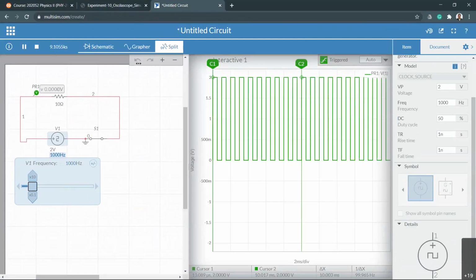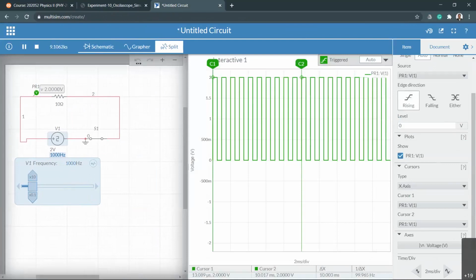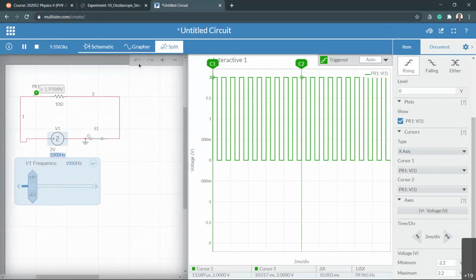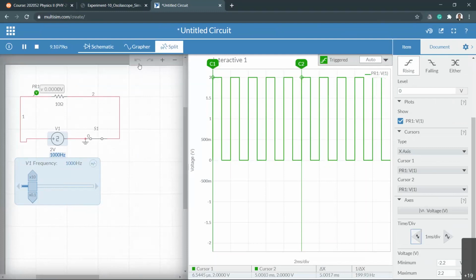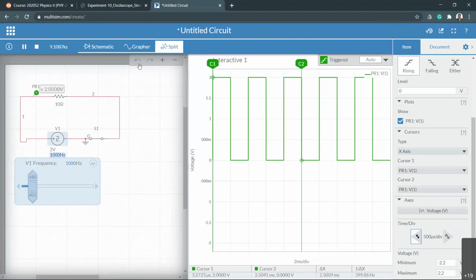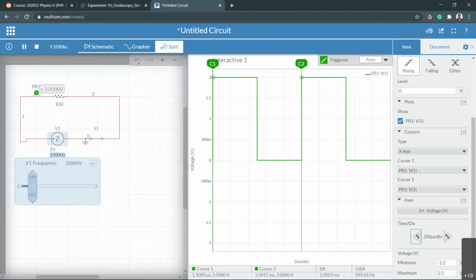And to get this x-axis operation, you can always click on the x-axis division per second point. Just click on top of that. Then the operation panel will appear. Then go downward right here, right-hand side, very edge. On the operation panel, click towards your left, more and more smaller time per division values until you see one nice complete curve, right? Then at that point, read 1 over delta x value.